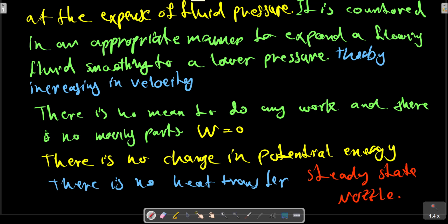An exception is the large nozzle on a liquid propellant rocket, such as was described in section 1.7, chapter 1, as an example, in which the cold propellant is commonly circulated around the outside of the nozzle walls before going to the combustion chamber, in order to keep the nozzle from melting. In this case, a nozzle with significant heat transfer is the exception and would be noted in such an application.